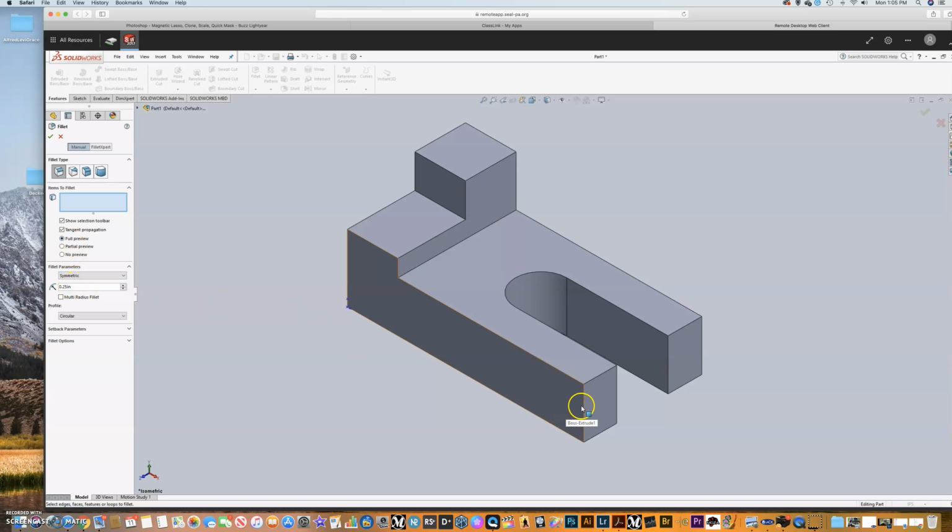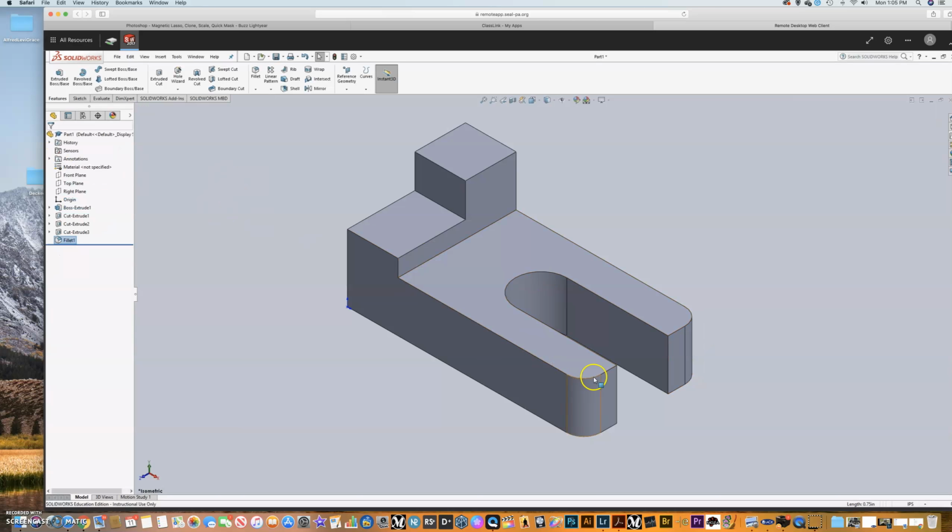And if you literally come down here and click this edge, yeah, it has to be here. It puts that on there. You're supposed to click this edge. If you make a mistake and you click the whole thing, see what it does? It does the whole thing. So the way you get rid of that, just click it again and it should disappear. And you come down here and click this. And click the check. And it puts that nice little fillet, that curved edge around there. And that's it. That's honestly the assignment.